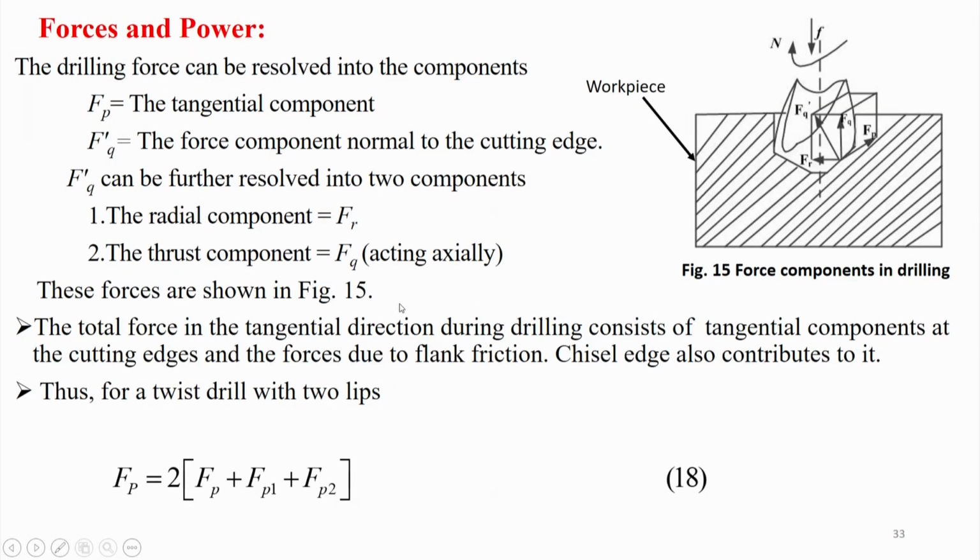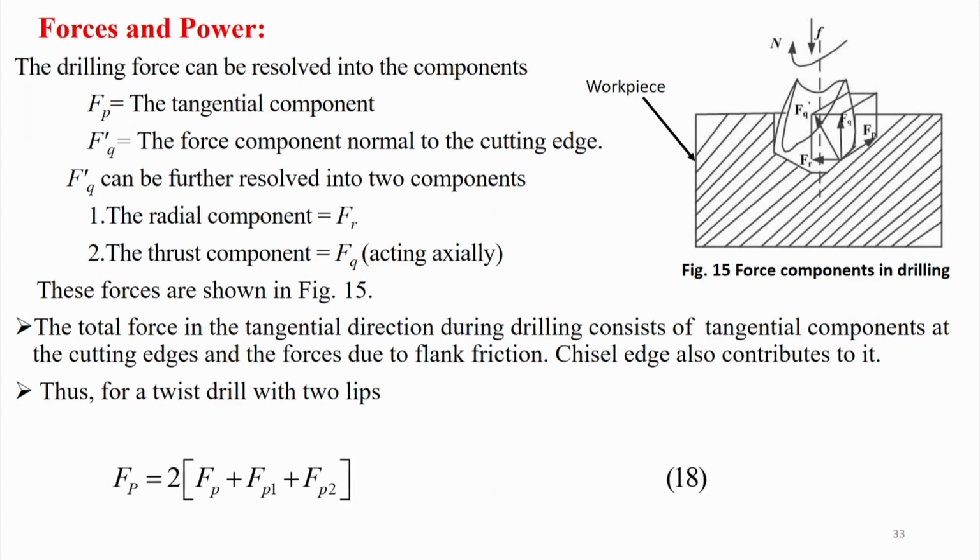Now, forces and power. The drilling force can be resolved into components. Fp is the tangential component, and Fq prime is the force component normal to the cutting edge. Fq prime can be further resolved into two components: the radial component Fr and the thrust component Fq. These forces are shown here.